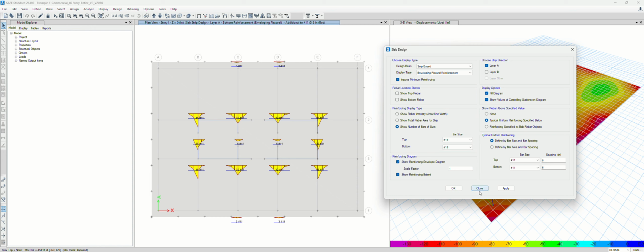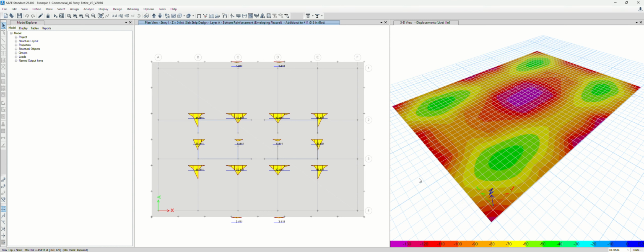So this is how we designed the rebar board. But basically, I want you to understand the same method, nothing different. Same as your spread footing design, right? Just look back, open your foundation design book, and see how you design the footings. Basically, based upon column load, divide by your footing area, right? Then you can convert your soil stress, right? Column reaction divided by the footing area makes soil stress.